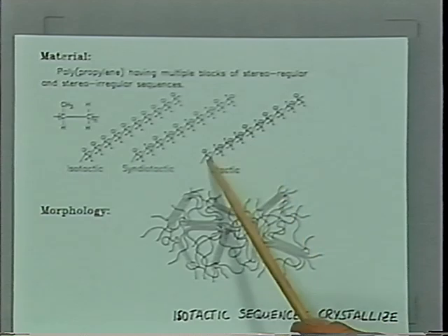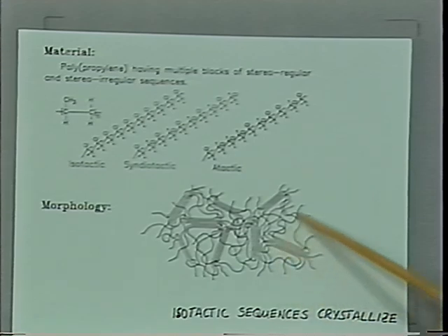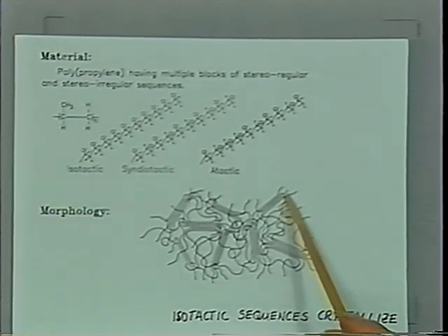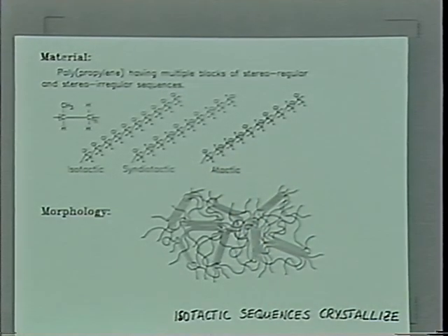So it's a good candidate to use rheological testing to go through the gel point. If there would have been an abnormal behavior in the melt already, you would not be able to expect the gelation transition to be somewhat normal. So in this case, he had long linear chains with isotactic sequences and with atactic sequences. The isotactic sequences would crystallize, and the size would increase as the time goes on. And the long chain segments, which are atactic, would form amorphous region. The whole system is a thermoplastic elastomer, which has interesting properties.